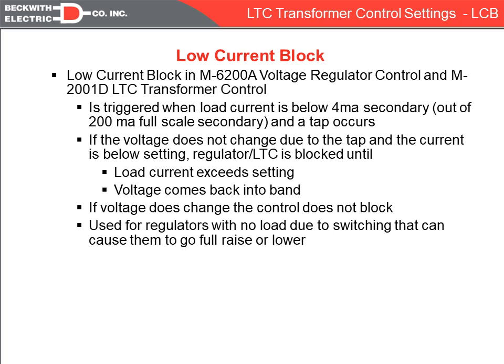The problem is there's no load current on those regulators, so there's not enough load for it to determine that it is in reverse power mode. So what may happen is if that little piece of bus voltage gets out of band, the regulator will attempt to fix it, and since it is on the wrong side of the regulator, it will not see that correction happen, and you could have a runaway condition, which doesn't hurt the voltage currently because there's no load on it.